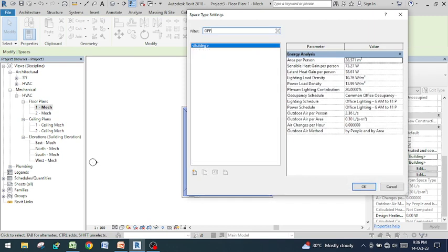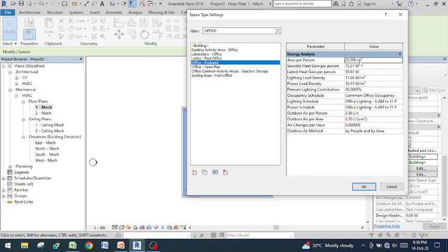In the space type, you can select that this is an office space. Just put the type office and closed office area plan. You can change these options here. HAP denotes the hourly analysis program. The same options are here. Occupancy schedule.